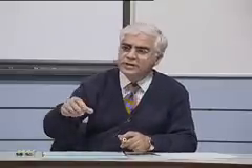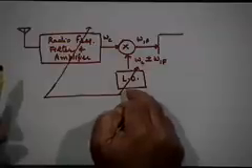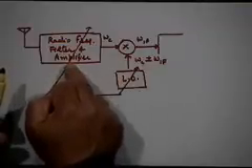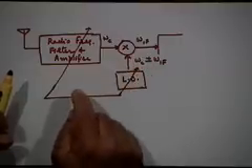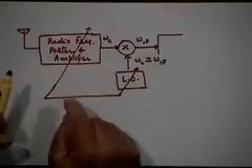In fact, if any of you has ever opened a radio set, you will see a set of parallel plate capacitors which are ganged up together. There are two sets of plates, and when you do tuning, both sets of capacitors move in and out, right. So that ganging up is done to change both the local oscillator frequency as well as the center frequency of the tuned filter here, so that the difference between these two frequencies is always omega IF, right. So that has to be done.